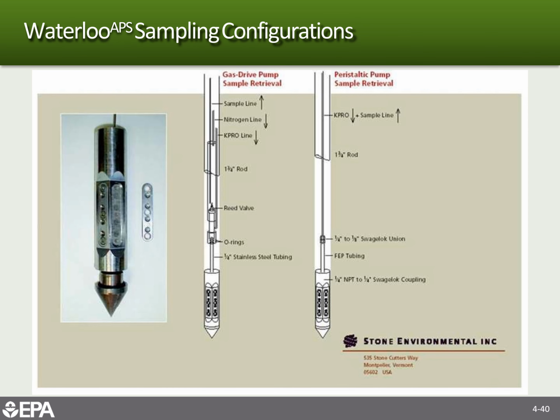This is a schematic where you actually push it down, and then you're able to adjust the tool from the surface and collect groundwater samples. I mean, this is all very much inch by inch, centimeter by centimeter, if you want to characterize to that level of detail. This gives you that high resolution data by using this kind of equipment.